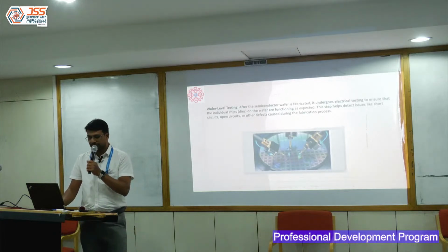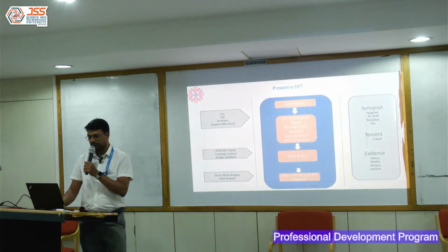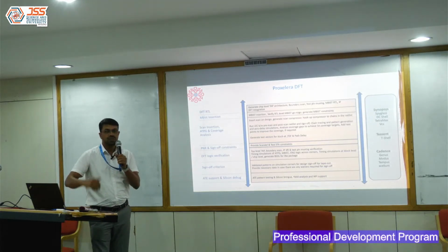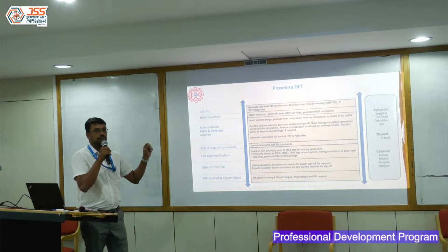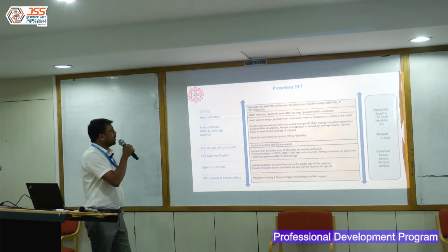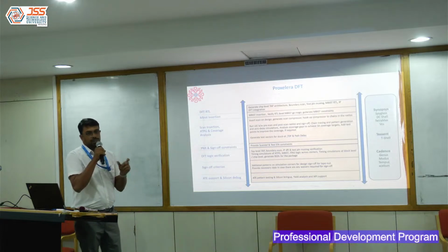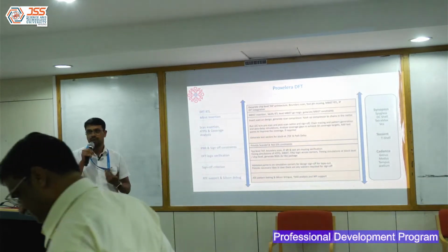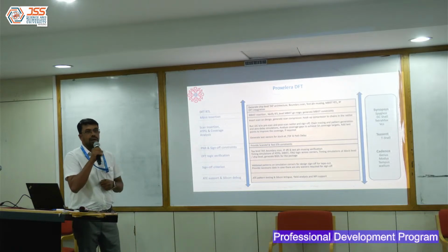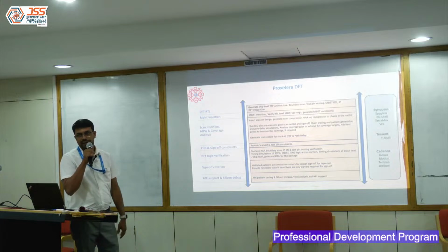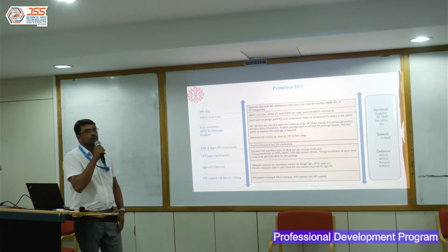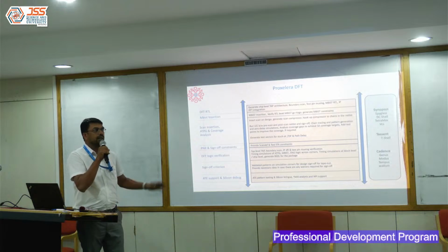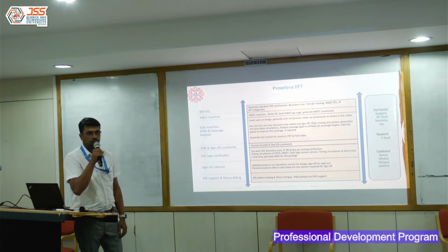So before I go into testing, I want to go back a few slides and just list out the different stages that a particular chip goes through during its phase. So basically, as I told you, it starts with the spec. The spec can come from customer or client, the way we address them. So they come up with the basic spec, or certain companies implement the spec in RTL and they come up with the RTL. Now from RTL, we do synthesis, get the netlist, and then it goes into the physical design flow.